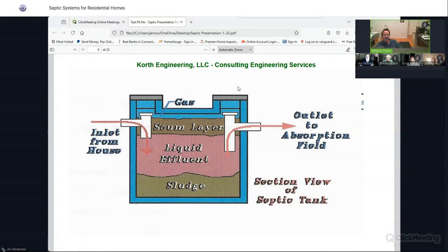And so there was discussion about venting the tank, the lids having a vent on it, and then to prevent odors, putting some kind of charcoal filter or gooseneck on that vent. And that somehow is supposed to save the upper top side of that tank and/or the concrete risers, which tend to be the areas of the tank that were deteriorated from the methane and other gases that are produced. Any opinion on that?